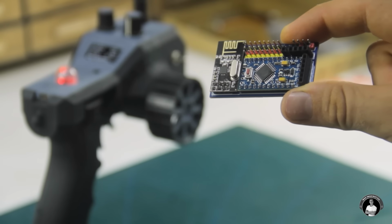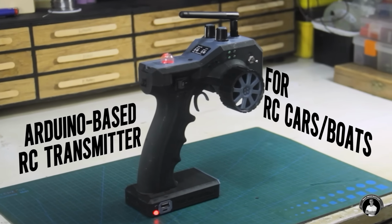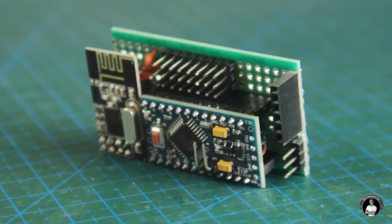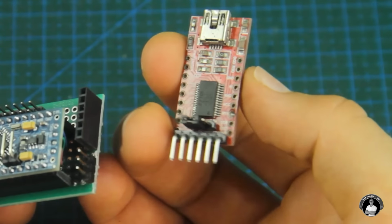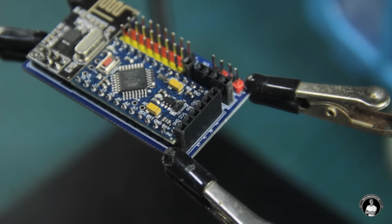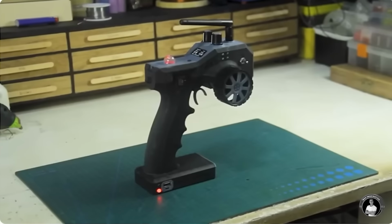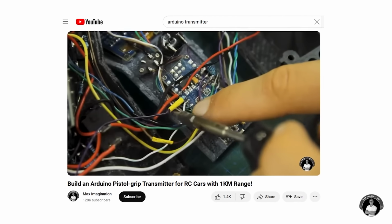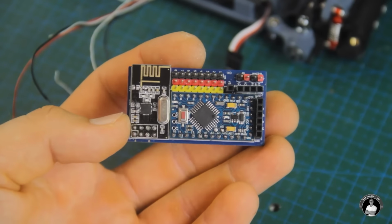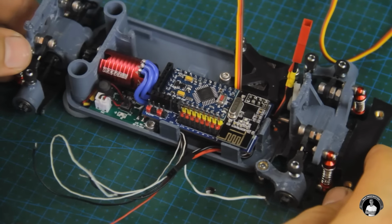The transmitter which will connect to it is this Arduino pistol grip radio transmitter, which used to connect with the Arduino receiver prototype in the last video. The new receiver gets programmed the same way as the old one, with an FTDI USB to serial converter connected to the female pin header. The receiver and transmitter code with more info can be found linked in the last video, which you can find through clicking the link below this video. Once programmed, the receiver can be clipped into place on top of the ESC without adhesives.